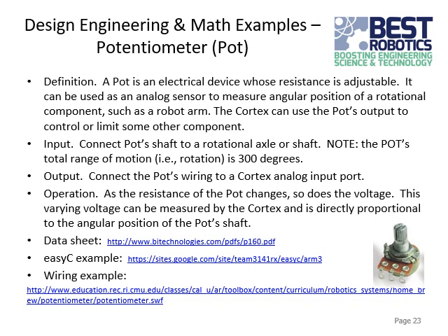And so you can use it to make an analog sensor that can measure the angular position of something that rotates, like a robot arm. You can put it along that axis of rotation and have it turn about that, and then you can connect wires up to the potentiometer and actually measure as it changes, as it rotates, so that your software can have an idea of where the thing is rotated to.